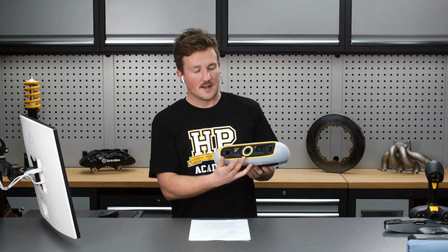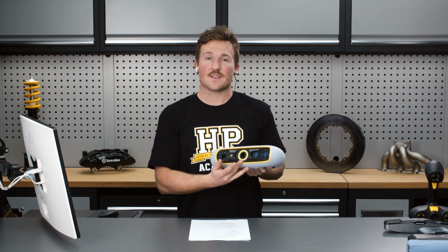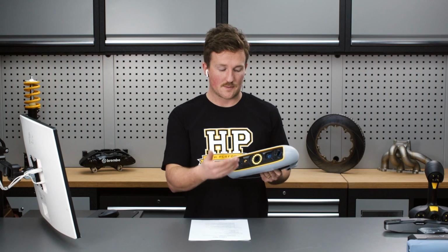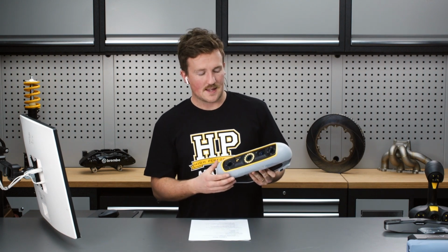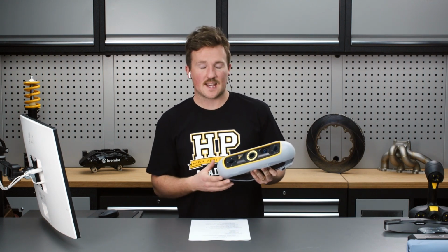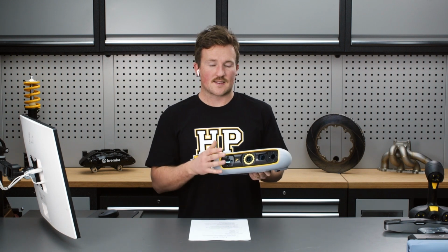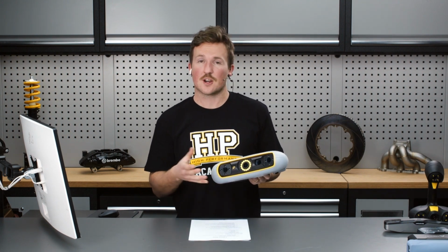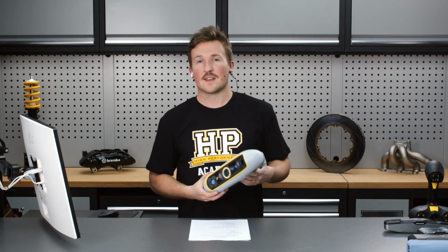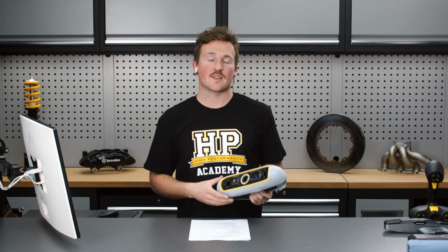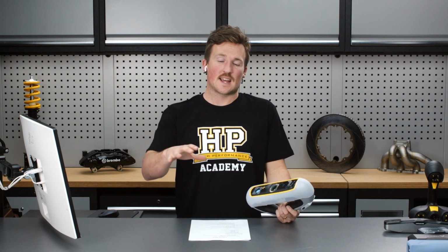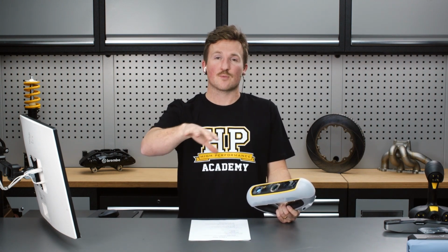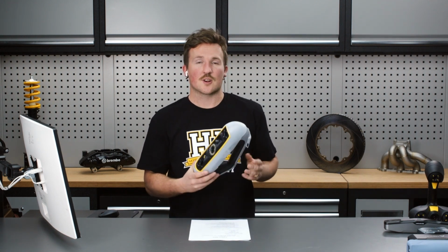Basically, we have a projector here that emits, for laser scanners, some laser light. And then we have two cameras here, which will be able to see via this triangulation how that laser falls onto the surface of the object, and then through the software or the programming of the scanner, it can understand from how that laser interfaces with the surface, the shape of the surface. So that's what triangulation is.